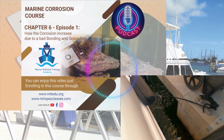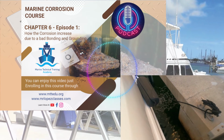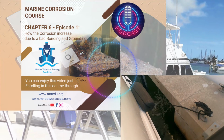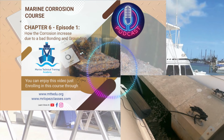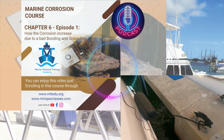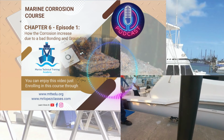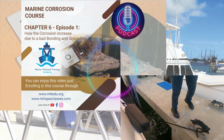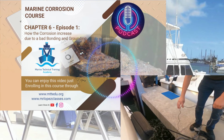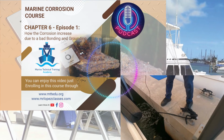In specific, in electronics, the negative bus bar, this one, is critical. In electronics, the negative bus bar is very important. If the negative bus bar is loose, if the terminals of the cables are improperly connected, if the cables are corroded, you introduce into the electronic equipment noise and interference.